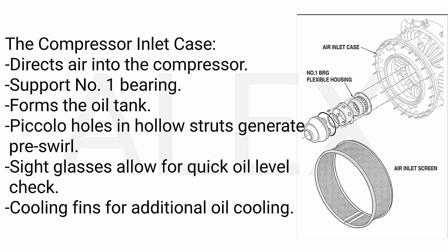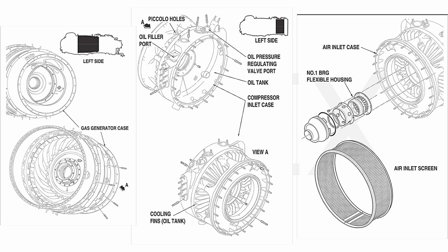The compressor inlet case directs air into the compressor. Support number 1 bearing forms the oil tank. Piccolo holes in hollow struts generate pre-swirl. Sight glasses allow for a quick oil level check. Cooling fins for additional oil cooling.